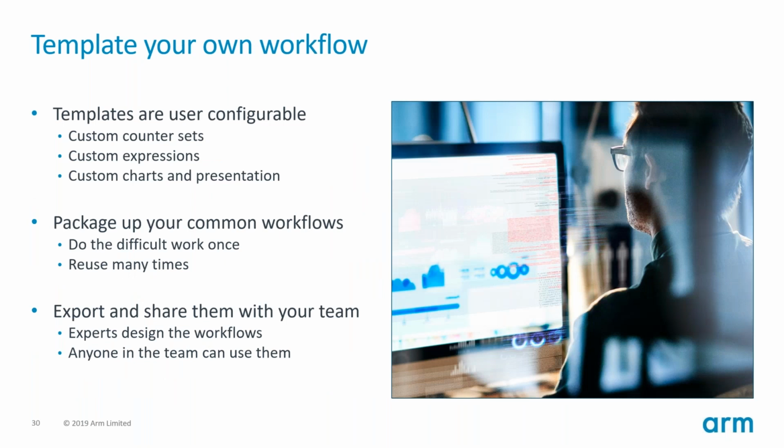Templates are configurable. So we provide some predefined templates for different GPUs. But if you want to customize a template for a particular type of CPU analysis or a particular kind of GPU analysis, you can customize them, you can save them out, you can share them with your team. So they're a really useful tool for packaging up a common workflow that your team uses in a form that's very easy to then reproduce. Single click to pick the counters, single click to visualize.